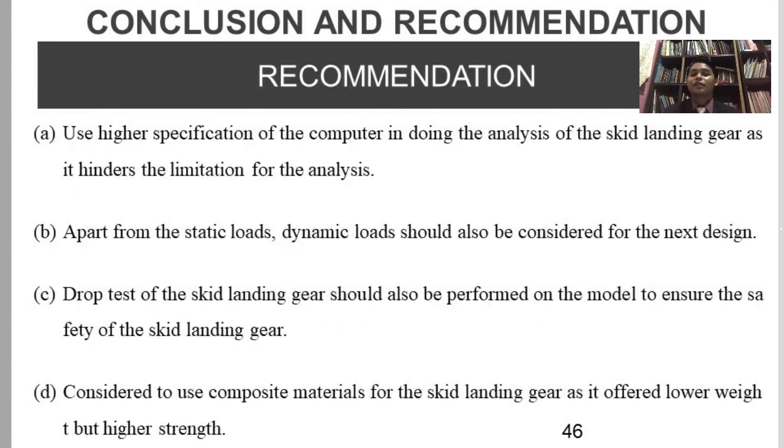So the recommendation for the next project is to use a higher-spec computer for the analysis, as it hinders the limitation of analysis. And apart from the static load, dynamic load should also be considered in the next design. Then a drop test of the skid should be performed to ensure the safety of the skid landing gear. And then consider using composite material, as it offers lower weight but higher strength.